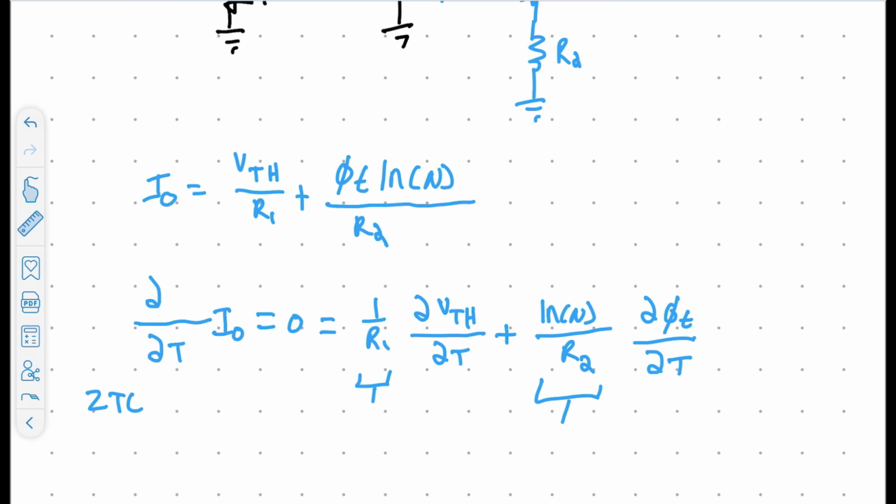But to get something a little bit more precise, you probably want to simulate this and get a more accurate number. And what you can do is rearrange these expressions and solve for a ratio of R2 over R1, and that'll be something that's probably close to, I'm just going to make a guess here, that R2 over R1 is probably going to be close to 15 or so.